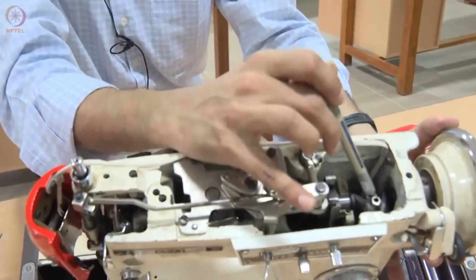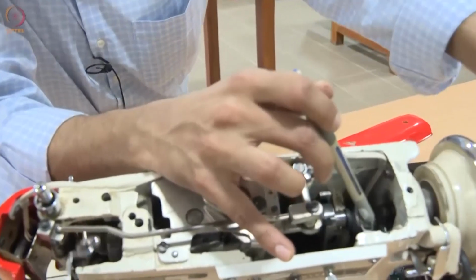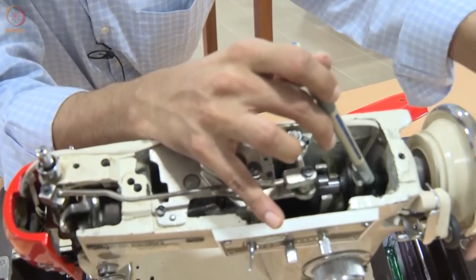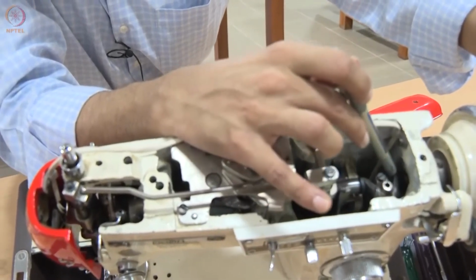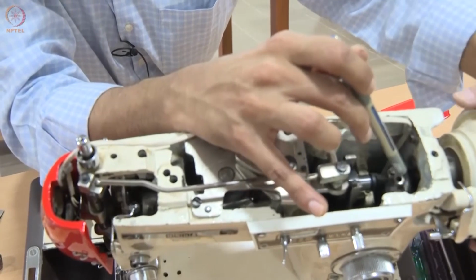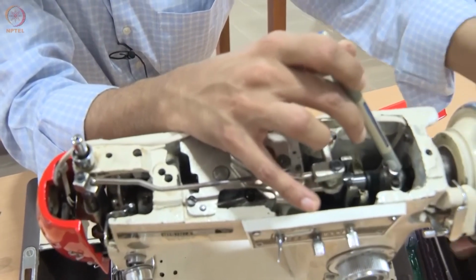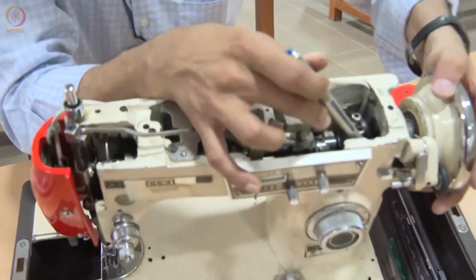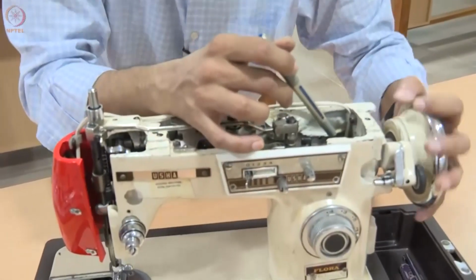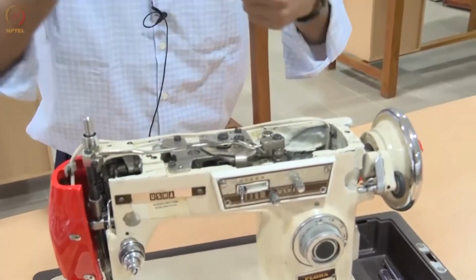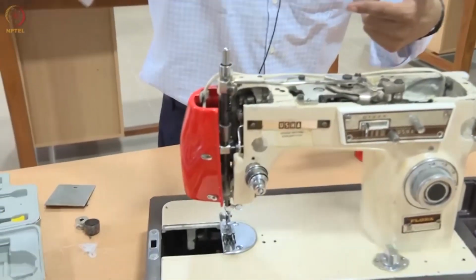So basically what this serves is, it creates a rotary motion such that this part goes up and down. We call this the crank, and then we have what is called the connecting rod. This part is called the connecting rod. I'll show you at the bottom, wherein the connecting rod connects to a slider. So this helps in converting a rotary motion into a linear up and down motion.